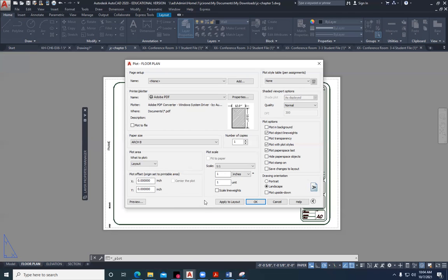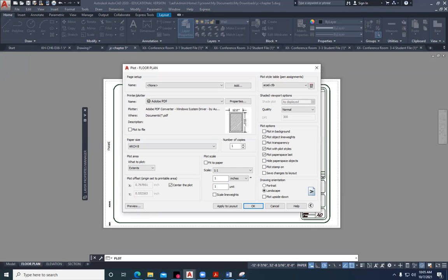And then as we look at how to plot a drawing like this, we can plot that by saying File, Plot. And we'll just say Continue. Now, plotters are tied to the printer. So last time that I used this title block, it was tied to a printer in room P134. AutoCAD configures the printers to the plotters. Now, if we want to print this to a PDF, I can say print to a PDF. Sorry about that, my computer's a little glitchy.